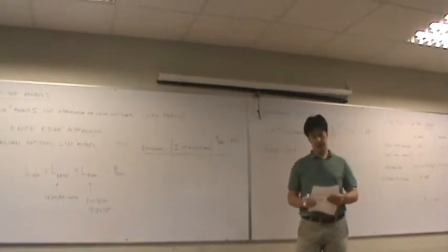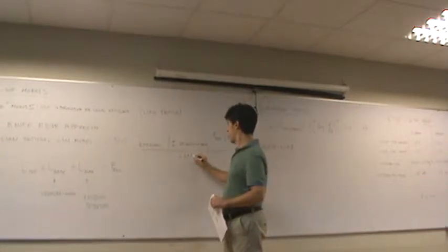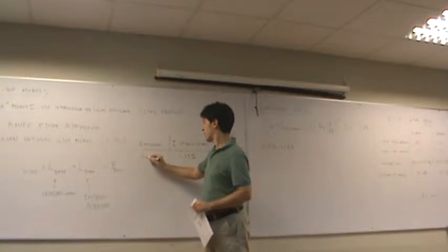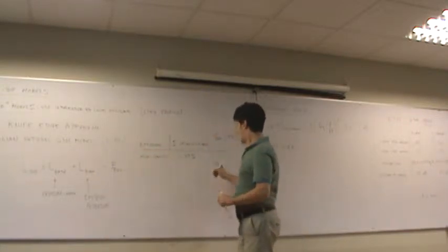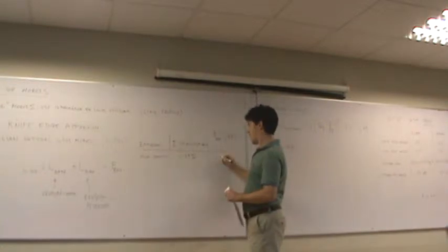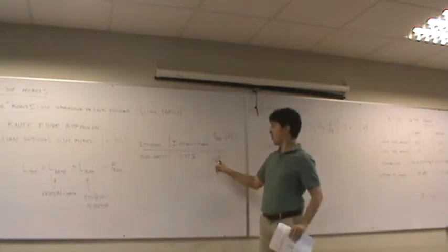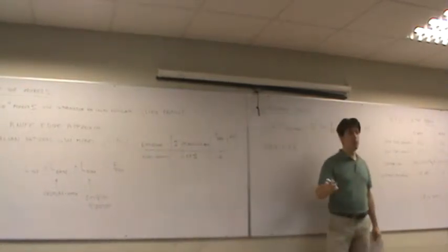So you take the percentage of built area. If it is greater than 35%, we say this is high density urban, and we introduce, look, the sign here is negative, so this will be an extra loss of 6 dB.